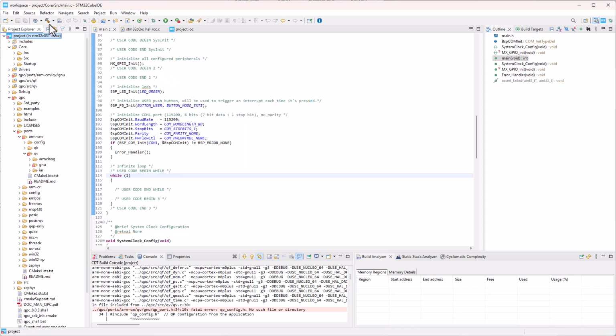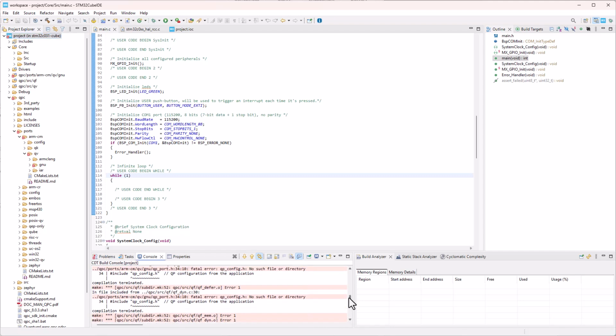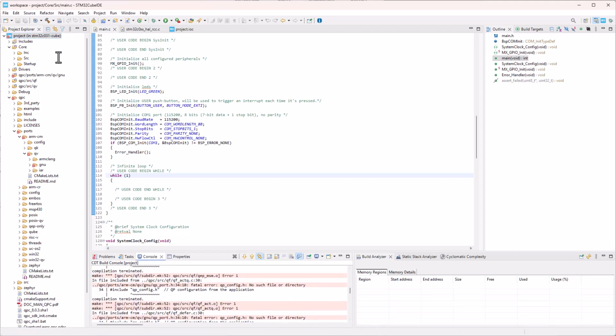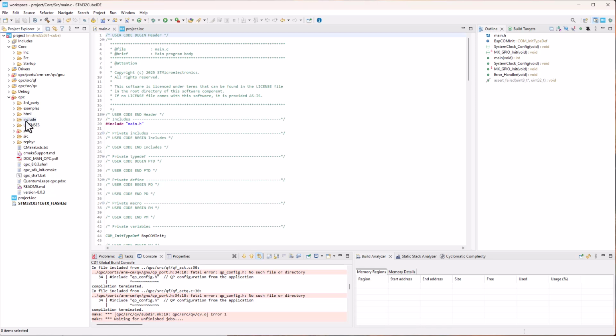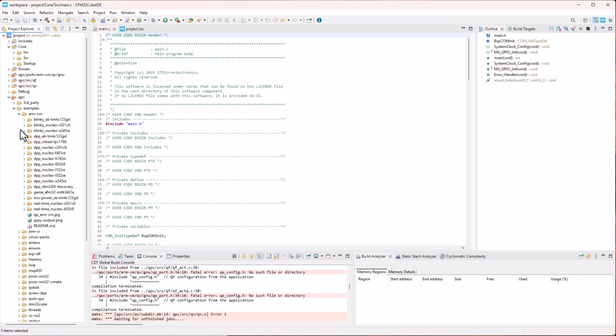When you trigger the build now, you can still see errors, but this time only one qpconfig.h file is reported missing. This file is not part of the QP framework, but rather the QP application you have yet to add. The application for today will be one of the standard examples provided in the QPC framework that you just downloaded and copied to the project. Specifically, the example is located in qpc, examples, armcm, real-time NUCLEO-C031C6, qv.